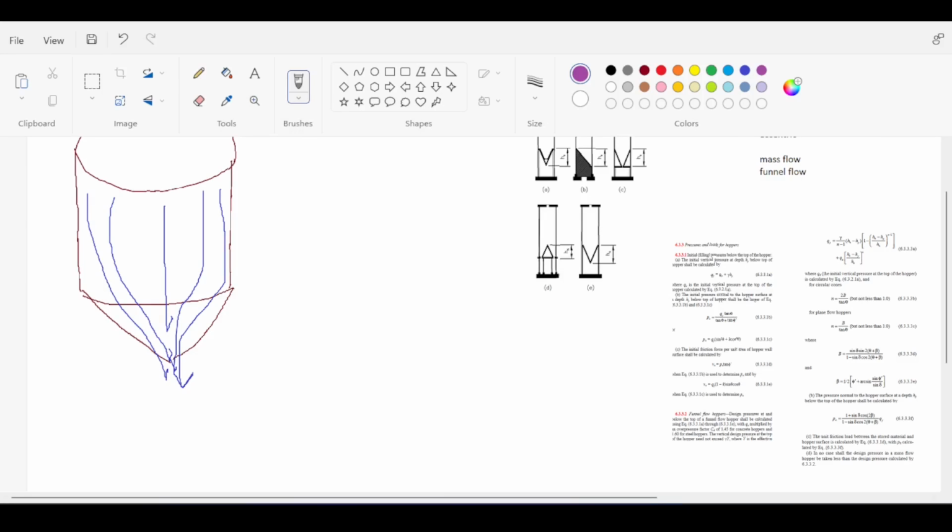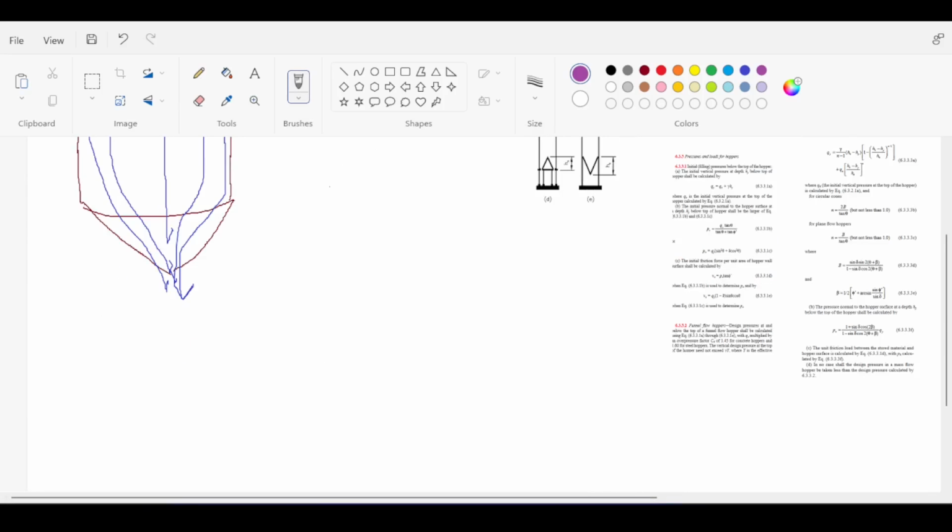So, okay, now there is a consequence here. Since your material is exiting from the bottom of the silo, you will have to keep your silo above the ground, which means you will have to provide a supporting structure. The supporting structure is usually made out of steel elements or concrete elements that surround the funnel, that surround the hopper, and basically is carried by columns, by 4 sides or 5 sides or whatever.